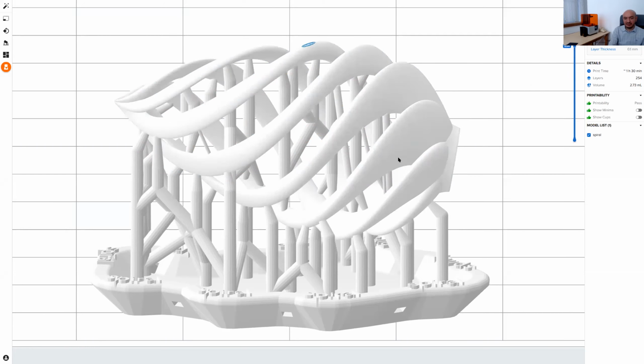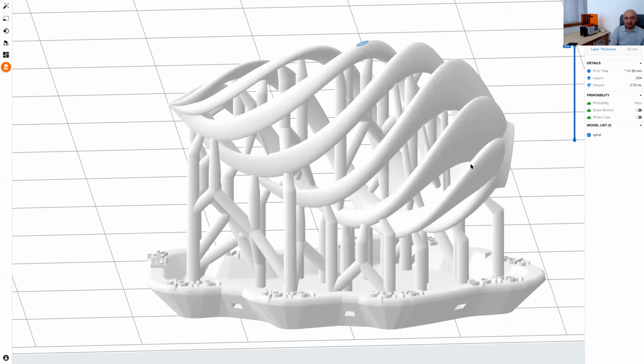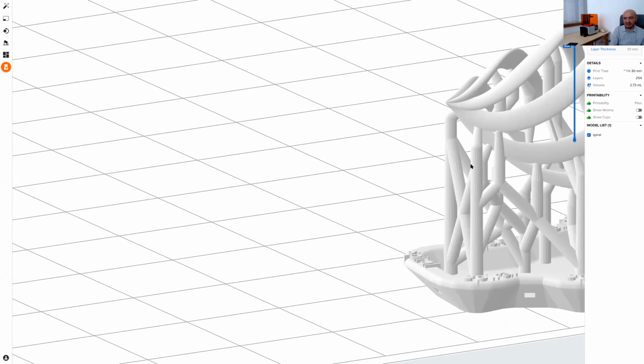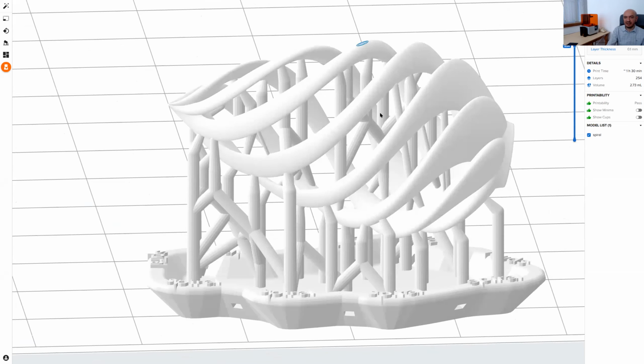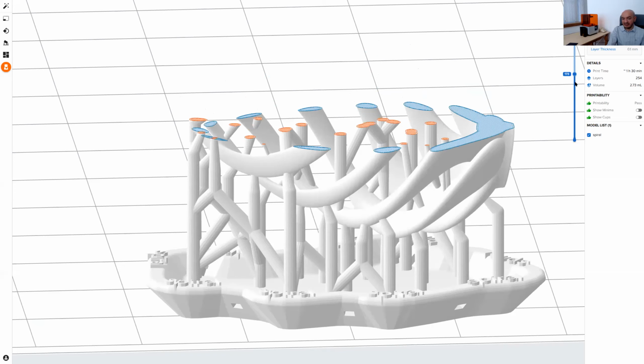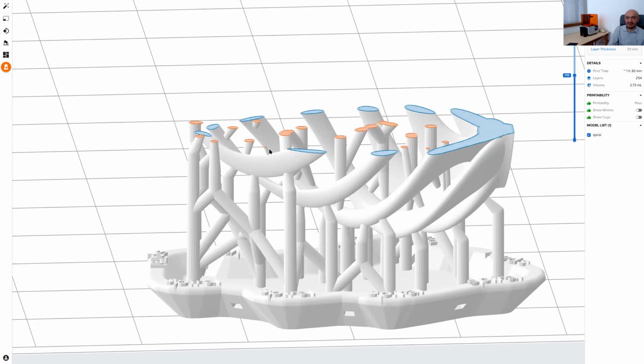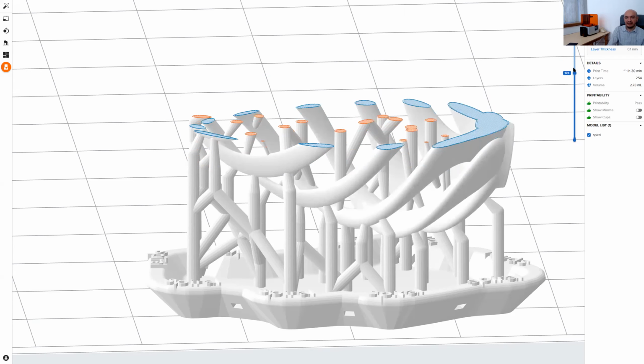After the part is printed, we need to do some support removing operation. And this will, I think, take lots of time. So I may keep it as it is and use it as a tool in teaching the SLA process. But this is actually how the printer fabricated the part. These are the layers. You see some support structures and the actual part.